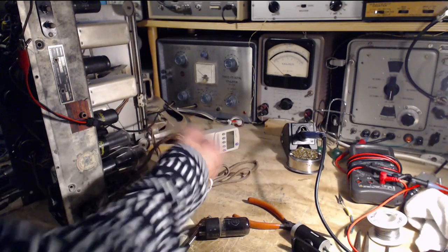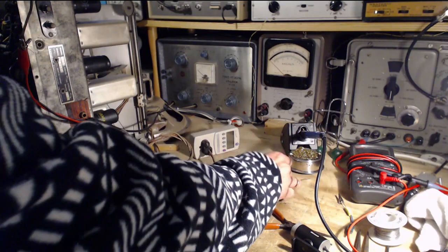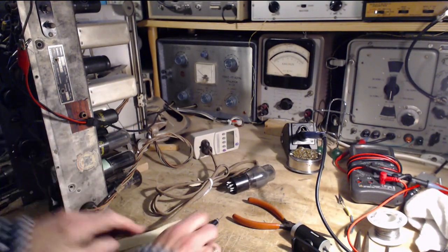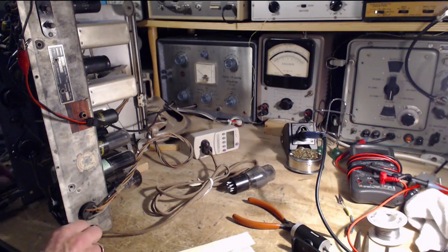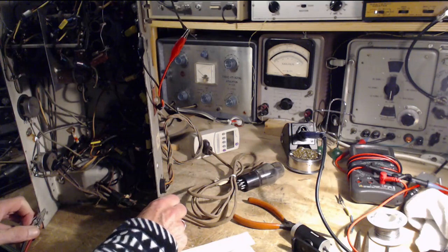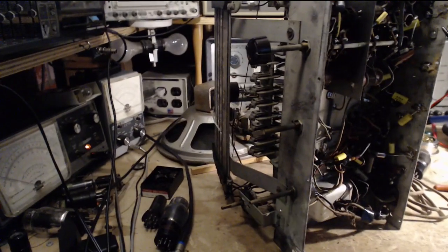And you can't mix two different tubes, that's for sure. That's not going to work out well. These tubes draw much less current on the heaters too, which is actually an advantage to the radio, because there's going to be less current going through the big power transformer. That's just going to cool that down a wee bit. Probably having an eyeball on those light bulbs is a good idea during this.